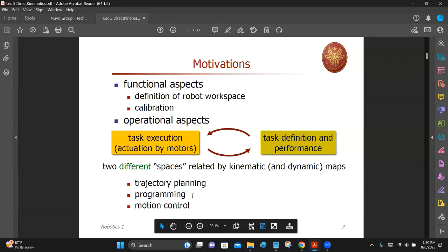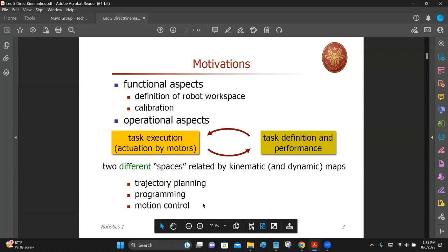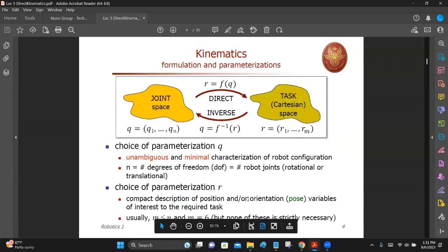Okay. So these things are actually embedded into the motion control system of the manipulator. You don't have to manually do that. All you need to do is to specify the via points, right? And after that, the control part of the system will make sure that the robot moves from one sampling point to the next sampling point within, say, 50 milliseconds. Okay. So it has PID controls, independent joint motions, right? To make sure each joint follows the trajectory. So that's how it happens.